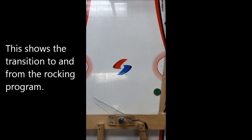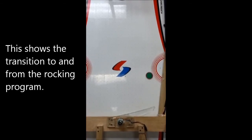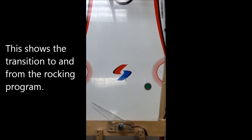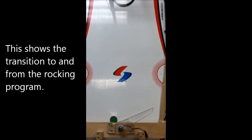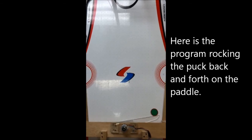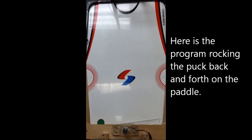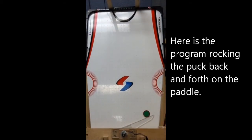This trick is called the rocker. It uses a closed-loop system that tracks the location of the puck on the paddle. According to the puck's location, the program tells the paddle to rotate to -50 or +50 degrees. We use a rate limiter to slow the speed of the motor so that the paddle will roll the puck and not launch it up.